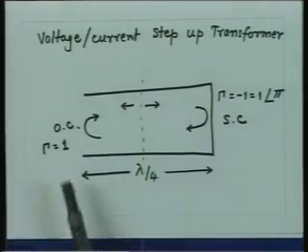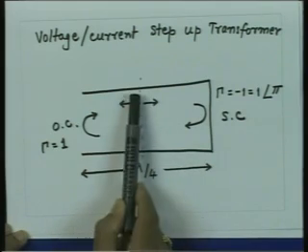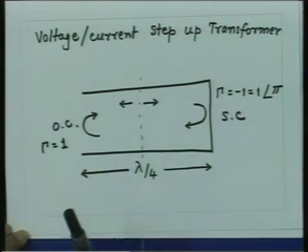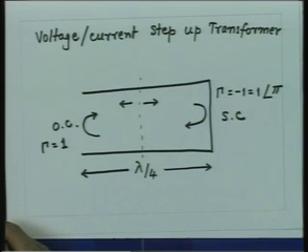But before this stage reaches, the voltages and currents have already reached to a substantially high value. So, even in practice, when the losses of the transmission line are small, one may generate very large voltages and currents, voltage here and the current here, by a small coupling source connected to the section of a transmission line.